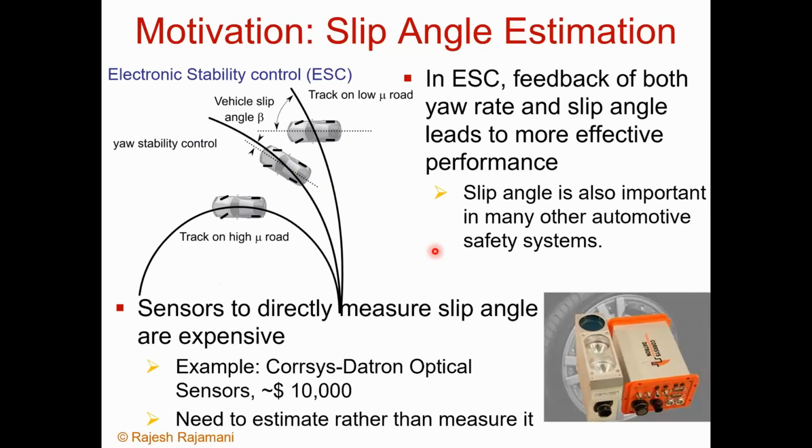So where is slip angle useful? Why would you want to estimate slip angle? One of the applications in which slip angle is useful is electronic stability control, sometimes known as yaw stability control. What is done in electronic stability control is differential braking.